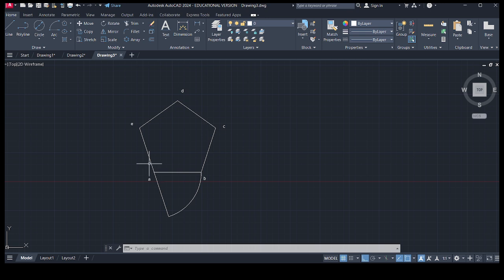Assume the periphery of the pentagon is wound by a thread. So we are holding our finger at point A and cutting the string at point B and unwinding so that it will trace the path. So it is nothing but the segment of a circle. Next we have to unwind the portion EA, the end of the line. So this is the radius of the circle and E is the center point.